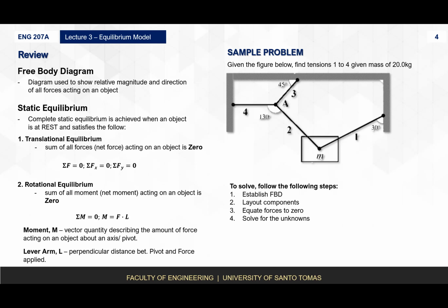Okay? Then once you lay out your components, you know what your X and Y's are. You now set up your equation. You equate them to zero. Since it describes most problems under static equilibrium, the summation of all forces will be equal to zero. So all you have to do is line up all the X forces and equate them to zero, then all the Y forces and equate them to zero. And then you create your equations or series of equations so that you can solve for the unknowns algebraically.